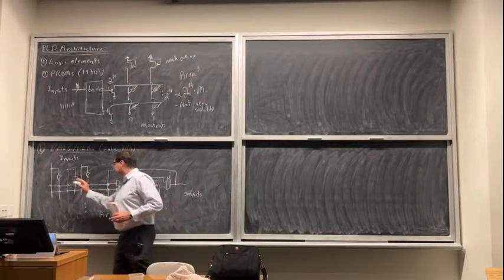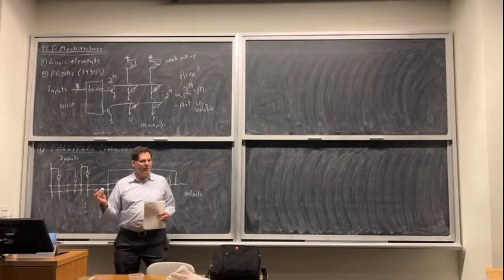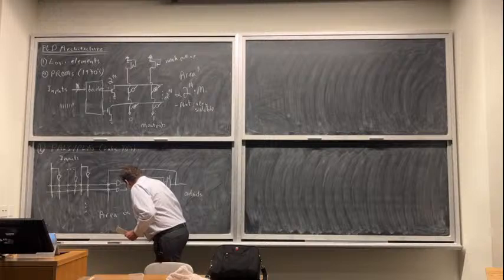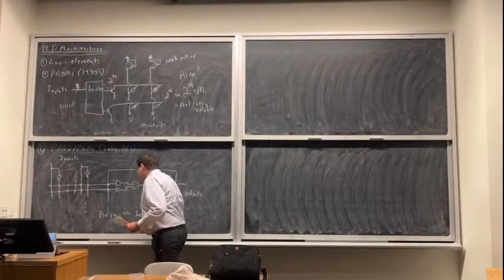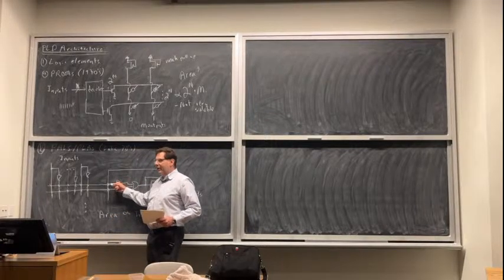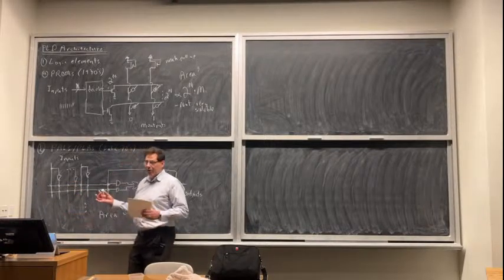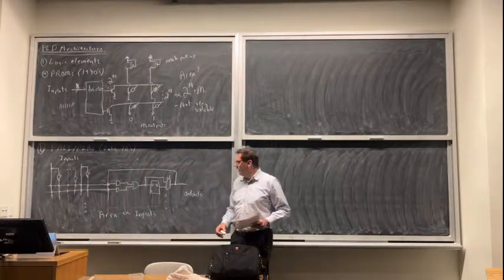So basically, my area is going to grow linearly with the number of inputs. Okay, so it's proportional to inputs, because if you count up the transistors in the AND gates, they'll go up linearly. If you count up the programmable switches, which also matters, that's also going to go up linearly.